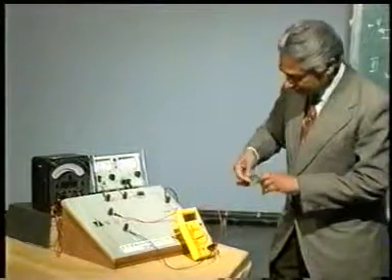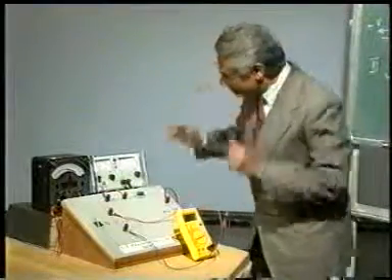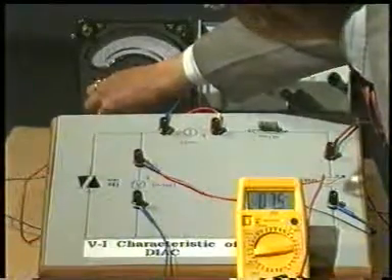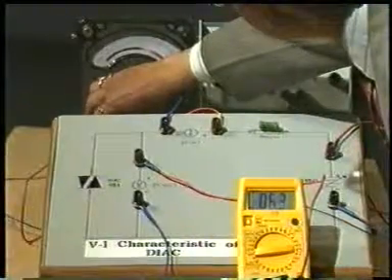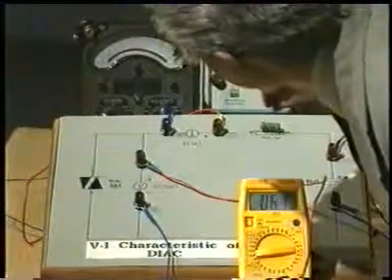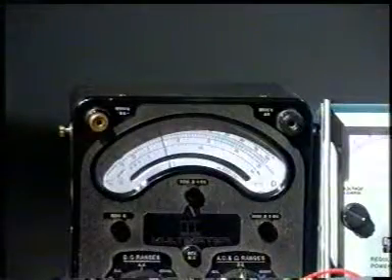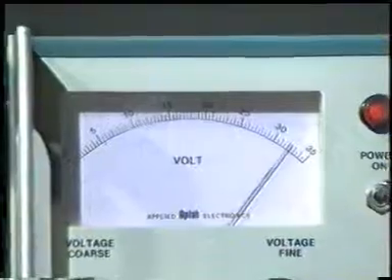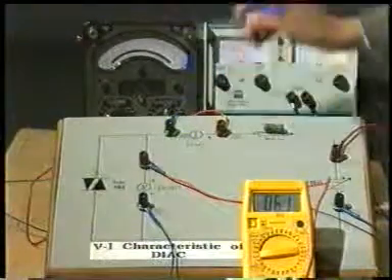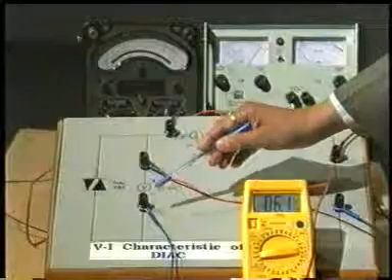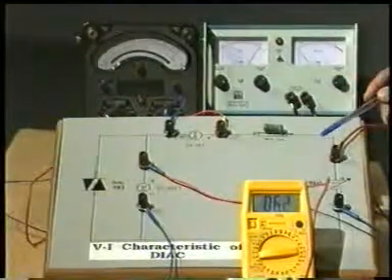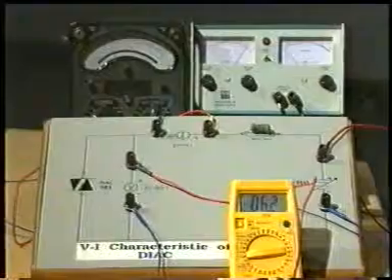Let me use my specs also. And it has gone a little out of range. So the value of the current is 0.3 ampere. The value of the voltage here is about 32 volts. And look here, the voltage here is 6.2. What does it mean? The VBO is 32 volts. The voltage dropped when this has conducted, that means voltage across the device after conduction is 6.2 volts, and the current is 0.3 ampere. I will write down the values for you.